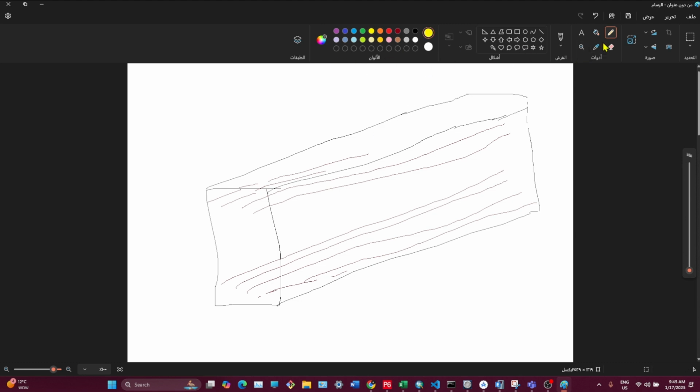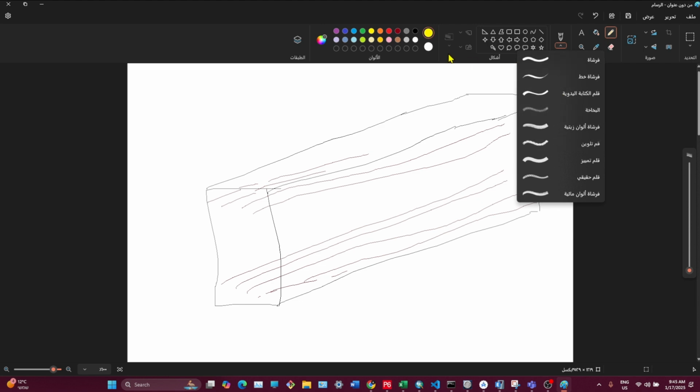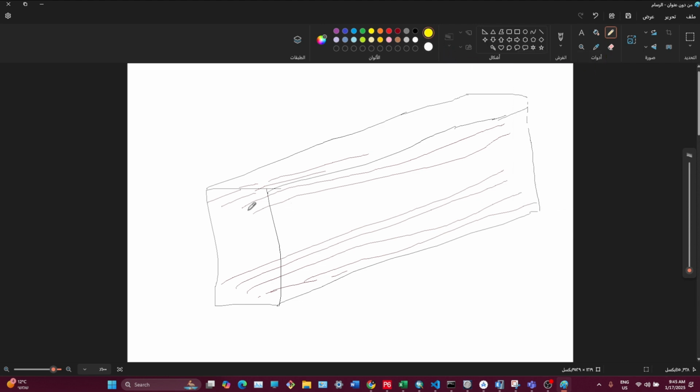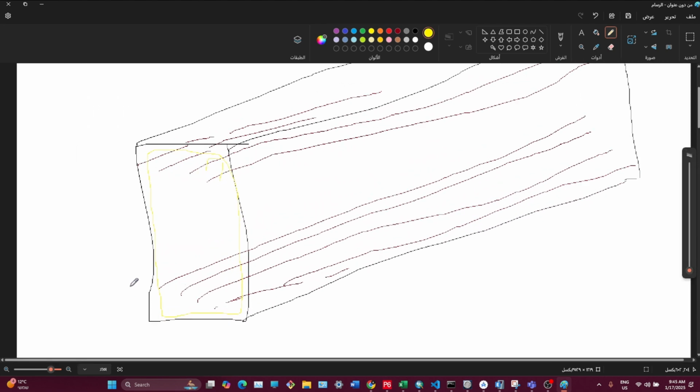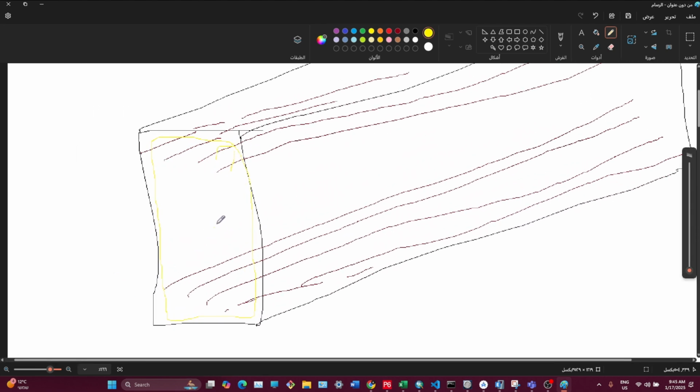Let's redo it. We can increase the line width. Okay, just like this, we have a stirrup here, and this is the hook of the stirrup. Is it clear? Yes. So this is the stirrup. This is the first leg, this is the second leg. So for these legs, assuming we have phi equal to 10 millimeter, then the Av is equal to 2 times the bar area because we have two legs that resist the shear. We have here the shear forces, the V ultimate, right?